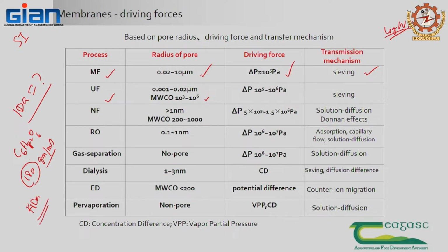So, for large molecular weight versus smaller molecules, you have to use ultrafiltration. That is again, micron is one thing and the actual criterion is molecular weight cutoff. Nanofiltration, reverse osmosis, all are gradients related to pressure. It does not mean that if you are using an ultrafiltration membrane, it will separate on its own, or that you exert a huge amount of pressure. If you exert a huge amount of pressure, still other things will also pass through.